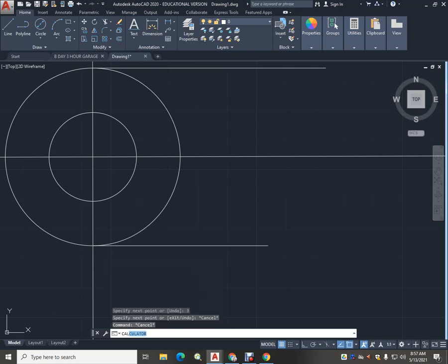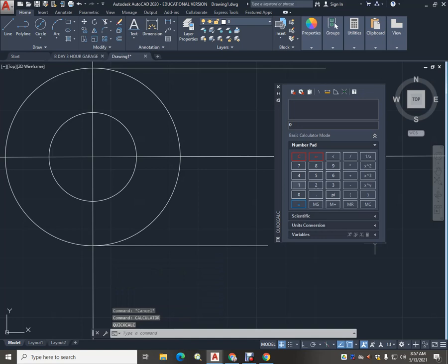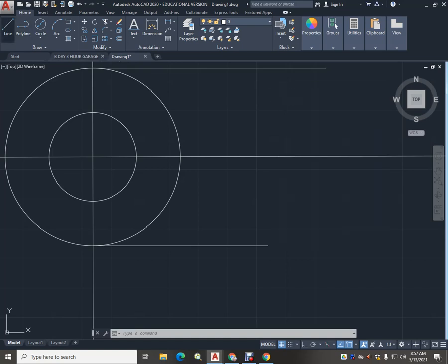And I know that a straight line is equal to 180 degrees, and we need to minus 45 from that, giving me 135 degrees. So let's do that. The line is 2 inches long. So hit the 2, now hit the tab key, and we want to type 135. That's what our calculator said. So let's put a dimension in there and let's verify that.